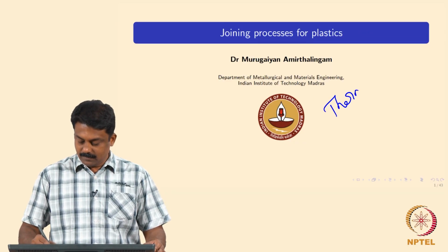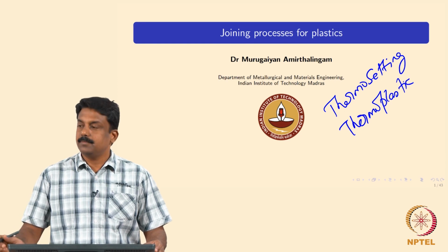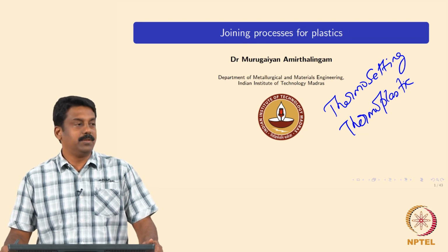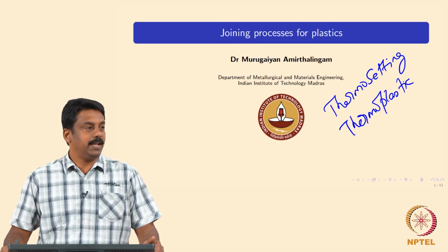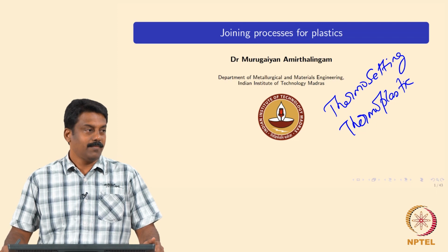We will look at, in this last unit, the processes that are commonly used for both types of plastics. What are the types into which we generally classify plastics? Two classes: thermosetting polymers and thermoplastic polymers. What is the difference between these two? Once you melt and shape a thermosetting polymer into a given design, it cannot be remelted and reworked. Examples?